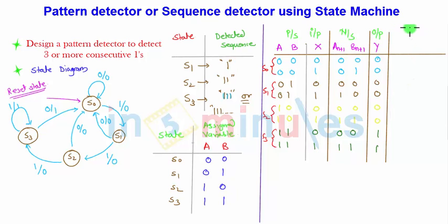Okay, now what I left this column for is the input to flip-flops. This is the flip-flop through which you are going to design the circuit. I am going to consider two flip-flops, since the number of tables required are excitation tables. So I will be getting DA. Let us design this whole circuit with the help of the D flip-flop.